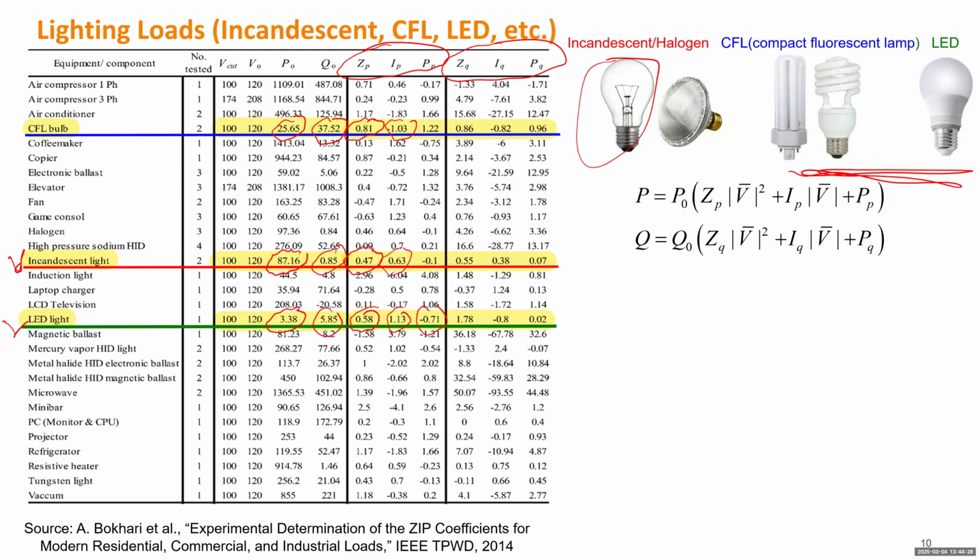And we only use that function to fit a small part of the curve near the nominal condition. That's why those numbers can be very strange. It may not have a good interpretation of what negative constant power means. That function may look very strange, but for the part around the nominal voltage, that's the best fit. That's basically a curve fitting method.